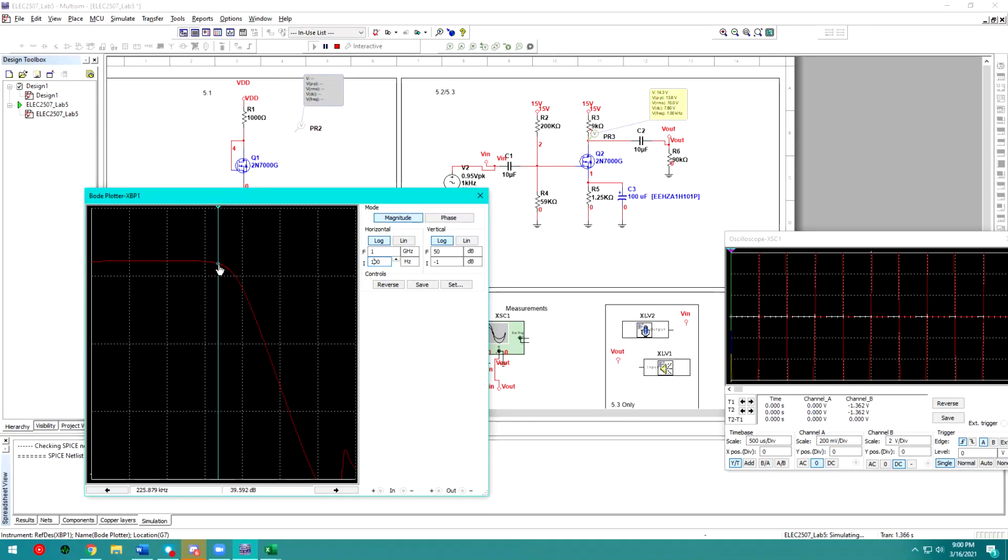And we can see that our 3 dB bandwidth is actually decreased, right? So from 40.5, we should be around 37.5, which puts our 3 dB bandwidth around 590.707K. So we have this steep decrease in bandwidth for the circuit, but we also have a large increase in gain.